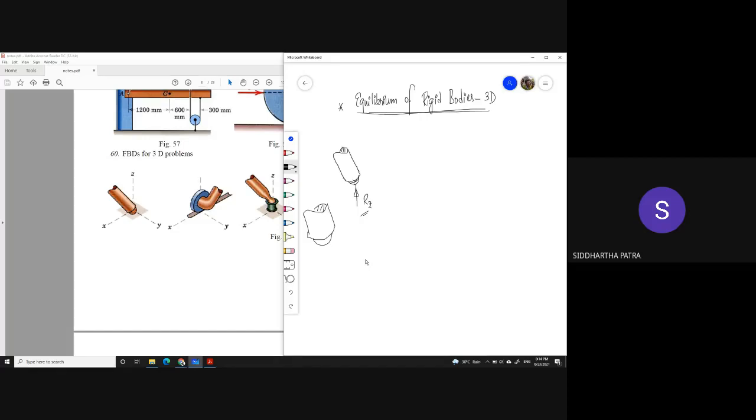But when you have a point contact, when you touch the plane of paper with the ball tip of your pen, there is no restriction, even with all the friction that the surface of paper can offer. The ball can rotate about any axis by any arbitrary amount. So there is no moment restriction on rotation, so there is no moment support, no moment reaction.